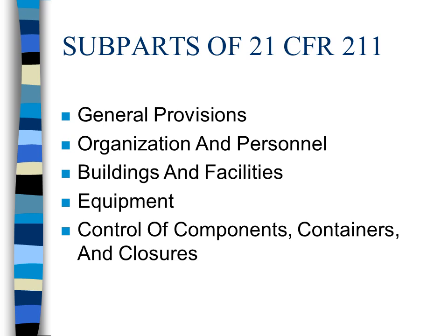For example, on your trucks, you are supposed to have your industrial cylinders separated from your medical cylinders. It's called segregation. In the warehouses, they have to have their cylinders segregated: fulls from empties, industrial from medical, and customer owned from company owned.